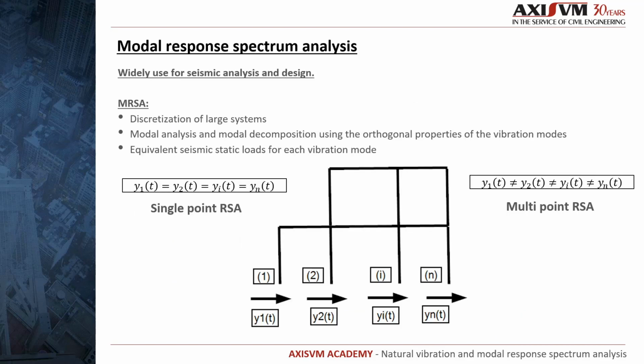So, the next topic we would like to present here is the modal response spectrum method. This method is largely used in seismic analysis and design due to its relative simplicity. The method uses discretization of large systems, does modal analysis and modal decomposition using the orthogonal properties of the vibration modes, and determines equivalent seismic static loads for each vibration mode. It is a simplified approach, but it can be used in many cases according to various standards if some conditions are met.